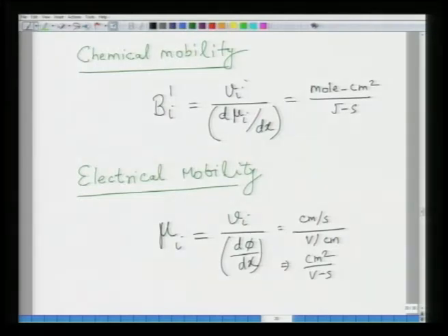Now, from the context of atomic transport, it was first Albert Einstein who pointed out that one of the most general driving forces for the atomic movement which acts in the diffusion of a species in a system is a virtual force. This virtual force is due to the negative gradient of chemical potential, or chemical potential, as you know from thermodynamic fundamentals, is nothing but partial molar free energy.